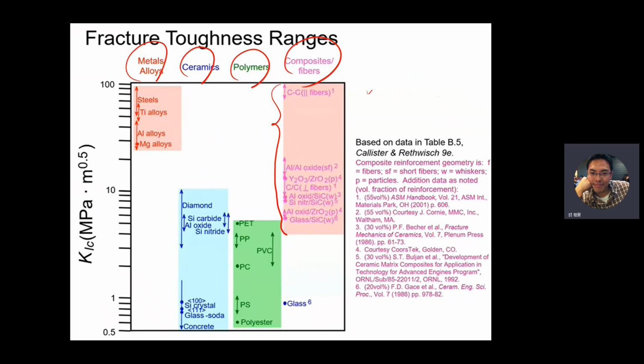Of course, if we have a higher amount of glass fiber in epoxy, we'll reduce the fracture toughness. You have to remember the definition of fracture toughness, which is the toughness of a material that already has an initial crack inside. So the glass fiber will reduce the fracture toughness of a composite, because glass fiber belongs to ceramics.